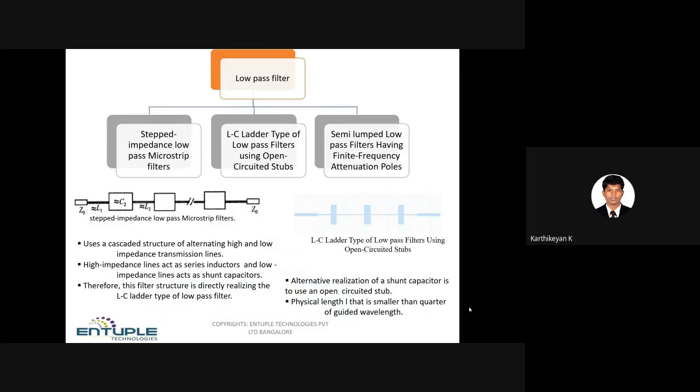There are different types of filters, like ladder type filters, or you can go for step impedance filter types. Here you can see this is a step impedance format. Input and output, and in between you can extend this structure. You can use certain LC components.